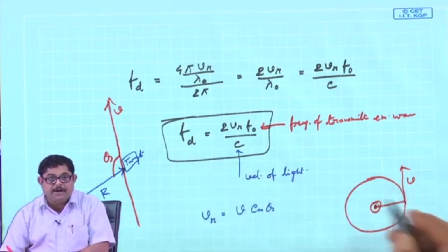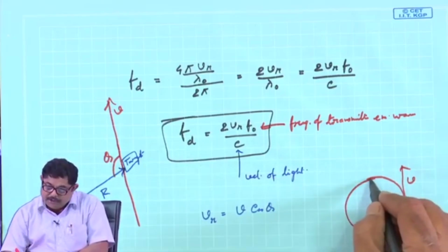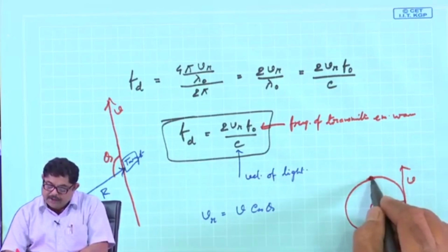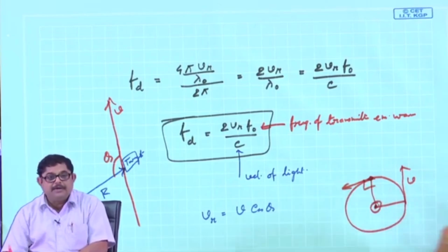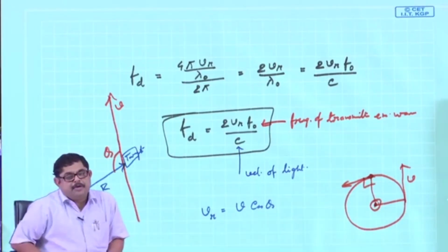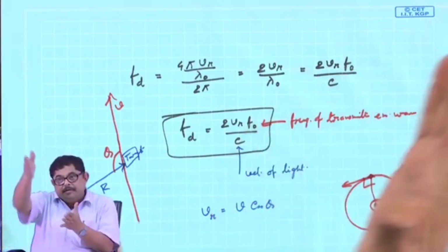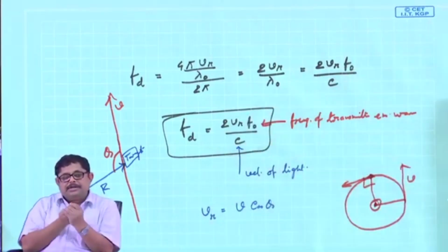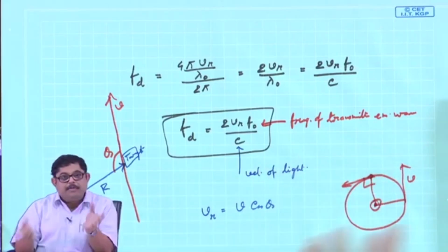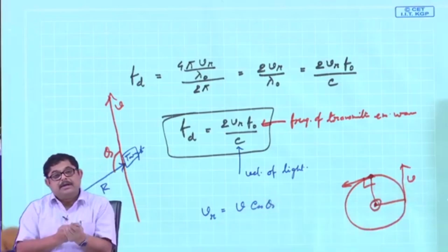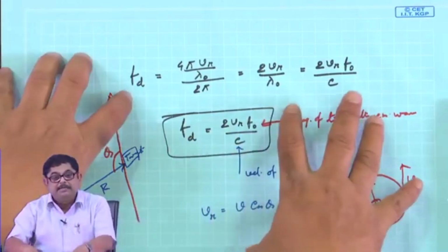So, that means Doppler shift is 0. Similarly, if the target is here, this is again 90 degrees. So, in this case the Doppler won't be there, but if you have any other angle there will be some component. So, that will come. Doppler shift when detected we will see, but this is the basic principle.